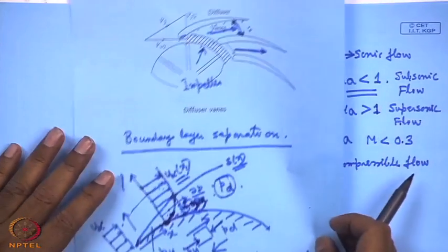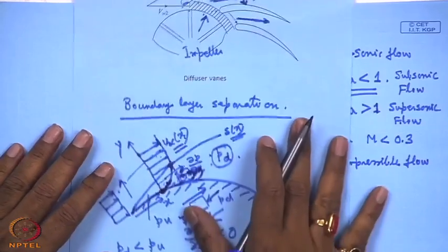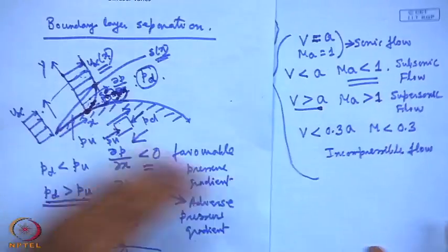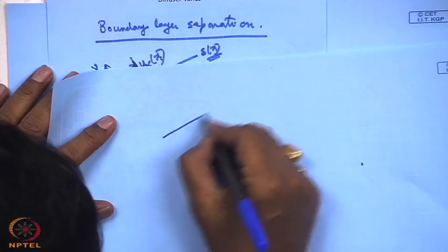So, from the practical point of view, that part of the mechanical energy, that means the static pressure, is being converted into intermolecular energy, which from the viewpoint of mechanical energy is a loss, and that is why people say this is the separation loss. Now, this was with the external surface. Now you consider a diverging passage, the same thing.